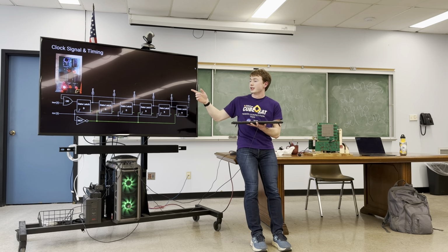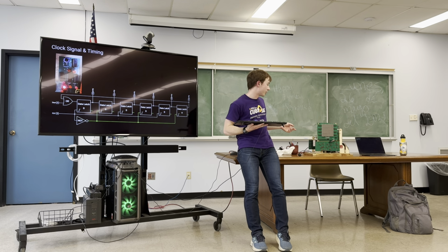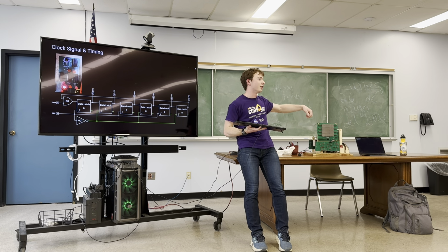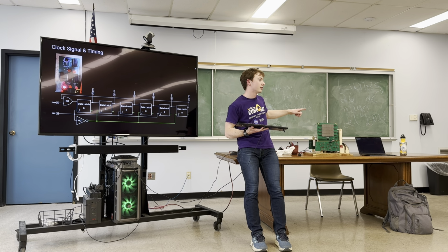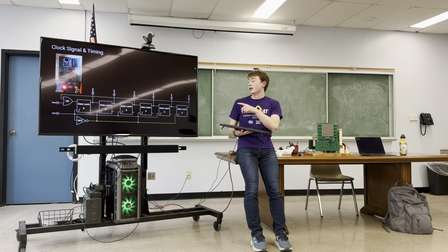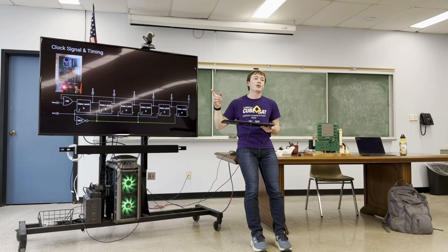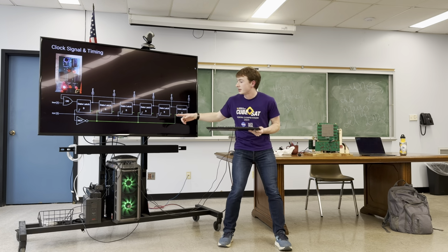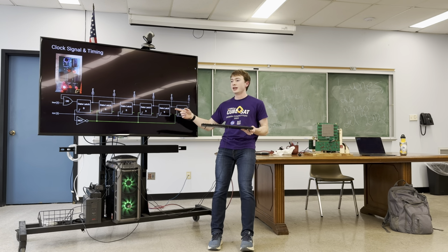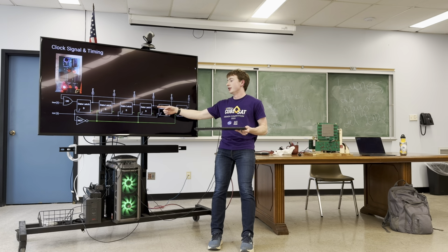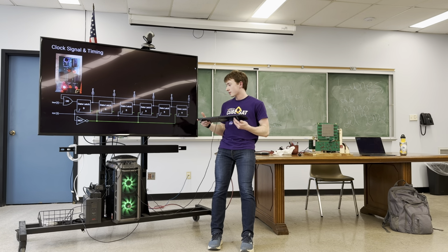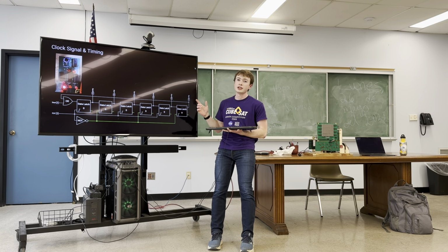You also need something to start it. That's why whenever I turn the computer on, there's a delay between when it receives power and when it actually starts doing things, because I have a big capacitor on that circuit board right there. What that's meant to do is, if any of these data latches were set to 1 whenever I turned on, I made sure to have an enable signal for the whole computer, and it's initially off when it turns on.